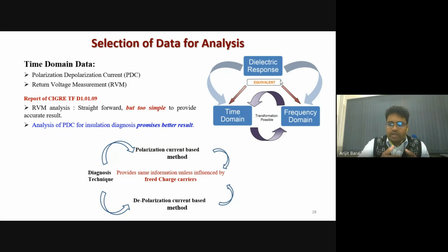So if the solid insulation becomes extremely wet, what we do, we put new oil into the tank, heat the oil up by some mechanism, and then we bring out the oil, demoisturize it, and then we put it back. So this to a certain extent dries up the transformer insulation, which needs to be maintained in its pristine condition.